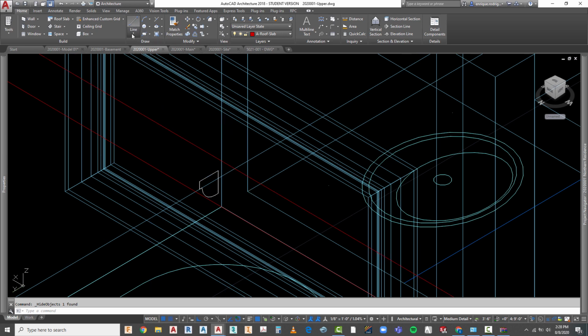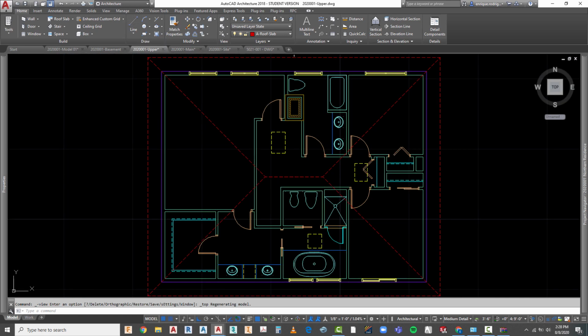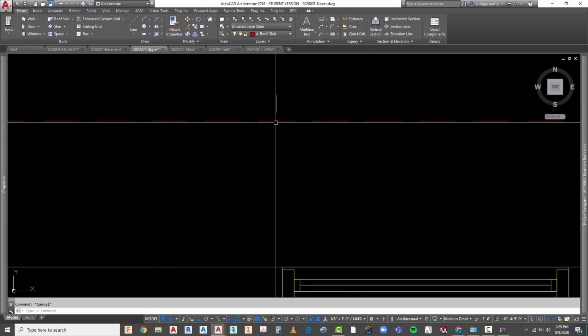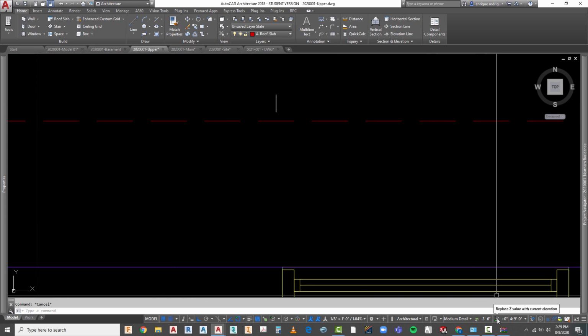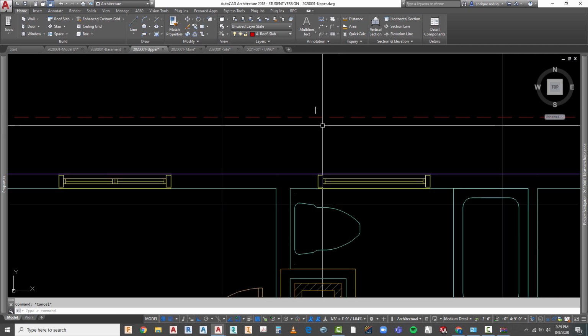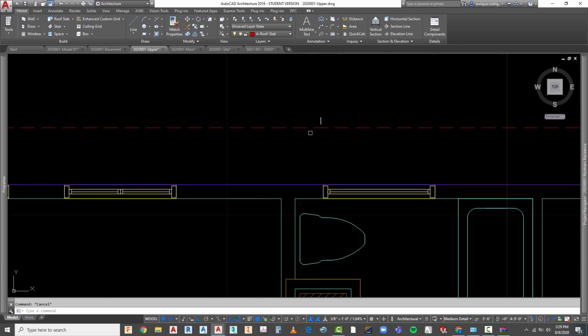So let's go ahead and create a polyline. I'm going to go up to the top view, and I'm going to start by drawing it right at this location. First of all, I'm going to turn this back on because I want to make sure that when I'm drawing these lines, I am drawing them at the correct elevation. If I have this on, I then just need to move the whole thing up in one shot. But let's take a look at what happens if I leave this on and I make sure that every time I draw this, I set up a snap point for it.